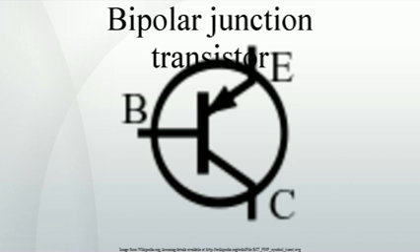The figure shows that this difference in band gap allows the barrier for holes to inject backward from the base into the emitter, denoted in the figure as ΔΦp, to be made large, while the barrier for electrons to inject into the base, ΔΦn, is made low. This barrier arrangement helps reduce minority carrier injection from the base when the emitter-base junction is under forward bias, and thus reduces base current and increases emitter injection efficiency. The improved injection of carriers into the base allows the base to have a higher doping level, resulting in lower resistance to access the base electrode.